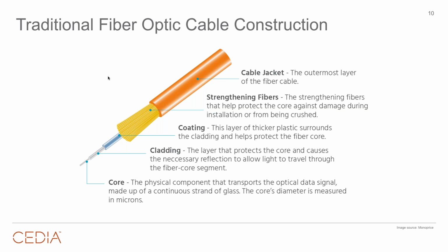Okay, and that Kevlar often has waterproofing gel that is built into it. It's coated on that yarn. So these fiber cables not only have incredible strength, and when I say incredible strength, I mean a 220-pound pull rating because of this Kevlar inside, but you also have waterproofing and the ability to have a wet rating because of the gel that's infused into this strengthening fiber.